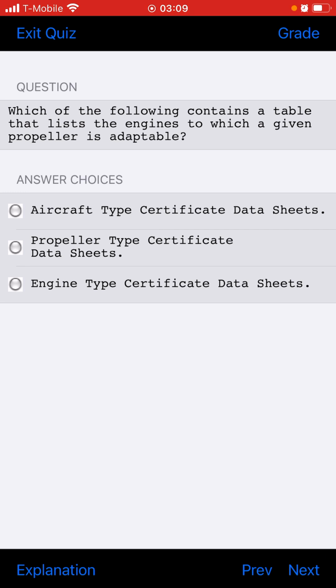Generally, an accurate trend forecast may be made after the engine first oil sample analysis. Pin section on the ground side of the electrical circuit. In order to reduce the possibility of grounding or shorting of the circuits when the connector is separated for maintenance, an AN or MS electrical connector should be installed with the pin section on the ground side of the electrical circuit.